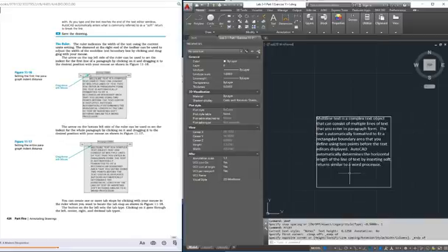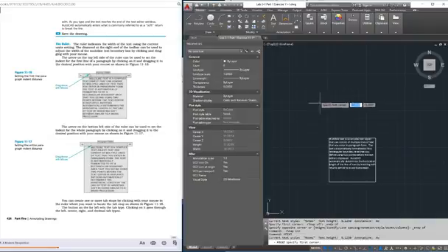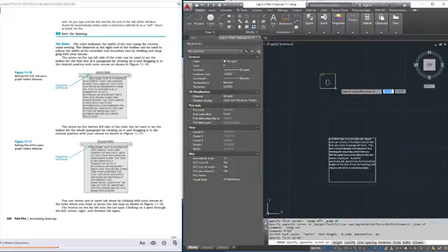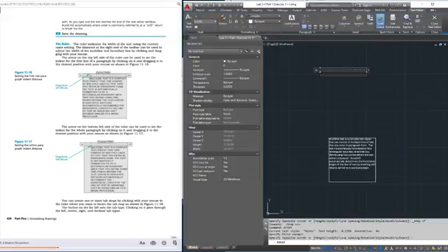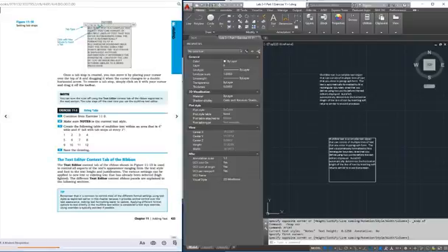And that's pretty good. So then if I want to do it with my snap, I'll hit F9, turn my snap on, and I'll do M text again. And you can see now it's snapping to about every inch. And I'll just go 1, 2, 3, 2, 3. And I now have a 3 by 3 inch text box. Then when you're done with it, you can just click off of it, and you've created a 3 by 3 M text window and put some text in there.